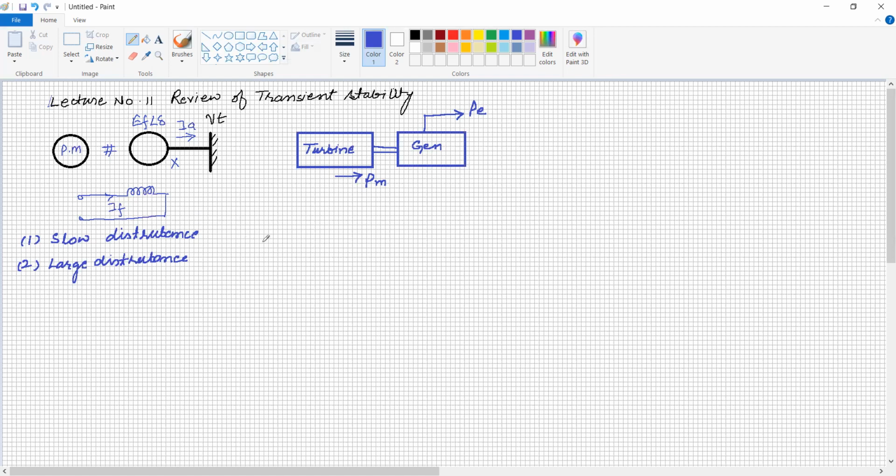The demand is going to decrease from 6 p.m. to morning 6 a.m. But the large disturbance is a sudden, unexpected change in the load. There may be a failure of a generator of 100 megawatt capacity or more that suddenly trips out. It may be the application of a fault in a 132 kV, 220 kV or 400 kV transmission line. If such a fault occurs, it comes under the large disturbance, and because of the large disturbance there is a transient in the system.